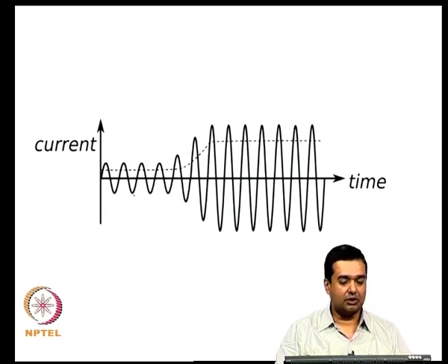That is what your ideal voltage is, a sinusoidal voltage. Ideally, your current is a sinusoidal current, going from a peak to a negative peak through 0. But if you look at it on an envelope basis or on an RMS basis, say if you have a fault, then on an RMS basis you could think about the current level increasing.